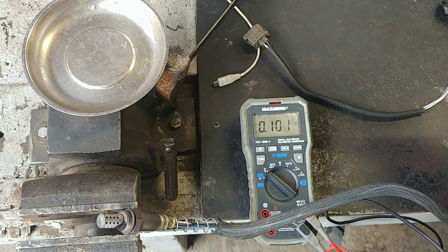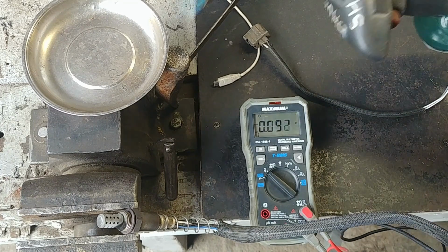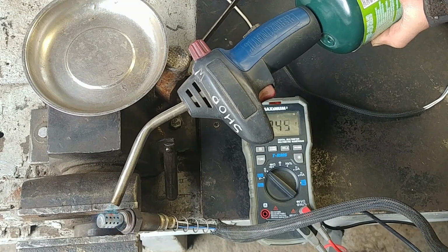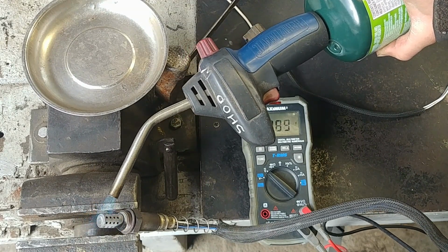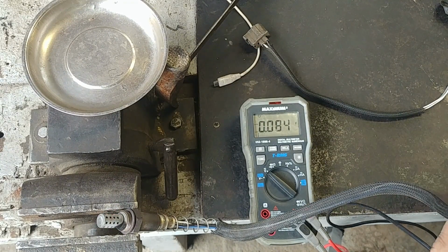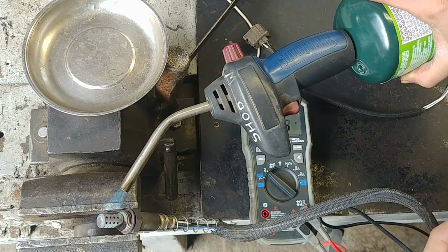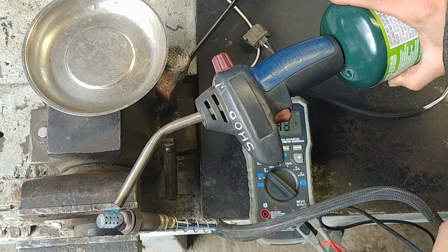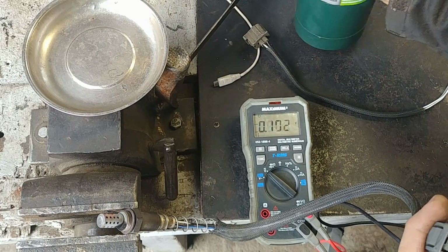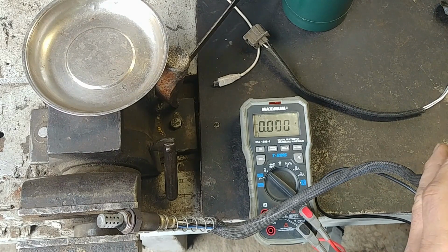Put out, almost 0. It means the less oxygen we have, or the more oxygen is burning right now, the higher the voltage goes. As soon as we remove the heat, we have more oxygen. The sensor is functioning at this point, but as we had a code, heater circuit high resistance,